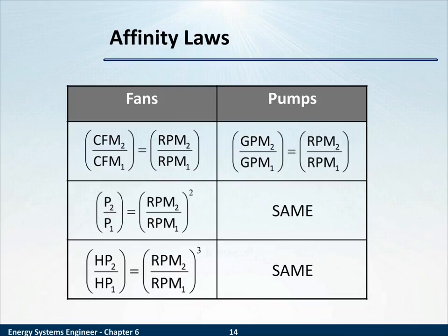The reason this is important is horsepower is something that takes energy. A typical conversion might be 0.746 kilowatts per horsepower. So if you can indeed reduce rotational speed or reduce cubic feet per minute, you can dramatically reduce horsepower.